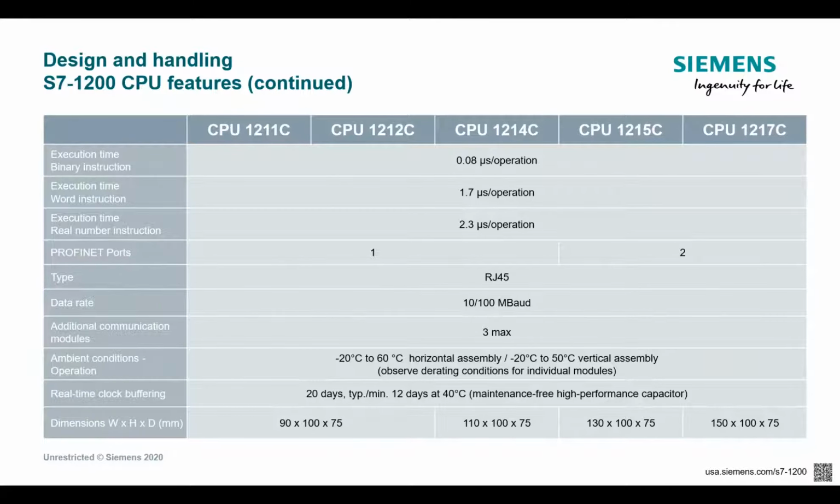It's not uncommon if you put a very large application into a 1200 with a lot of distributed I/O, several different Ethernet VFDs, remote I/O racks, you can start to see scan times grow into the high 60s, 70s, even above 100 milliseconds. And so just depending on your application, that may or may not be acceptable. And so that's something to keep in mind.